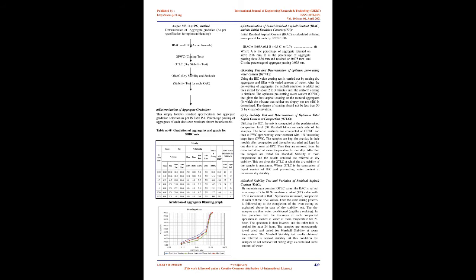B. In the study, dense bituminous macadam, SDBC, cold mixes were prepared. Selection of materials and aggregate gradations was as per specifications specified later. For compaction of cold mixes, the Marshall compaction method was followed as per MoRTH, 2013, and IRC SP 100, 2014, specification. The procedures are summarized below by flow chart.